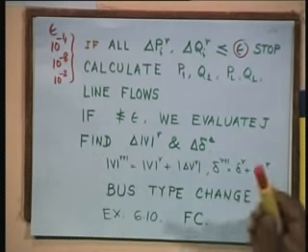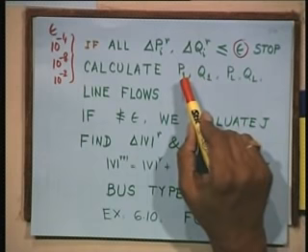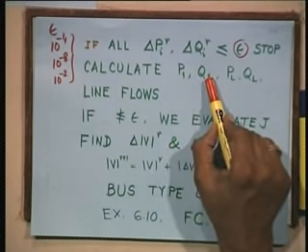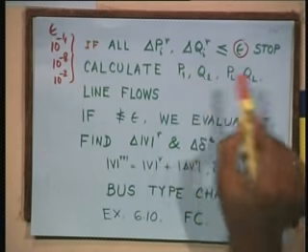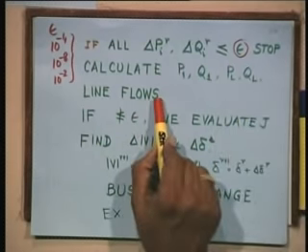You may have to work in a load dispatch center, you may be going to Power Grid, you may be going to BHEL, NTPC, NHPC, Central Electricity Authority, or Tata Electric companies or any private companies. You will have to solve load flow again and again, because that is, as I said, your bread and butter. Calculate finally what is the outcome of a load flow solution: the slack bus power, real as well as reactive, the losses, real as well as reactive, and line flows.